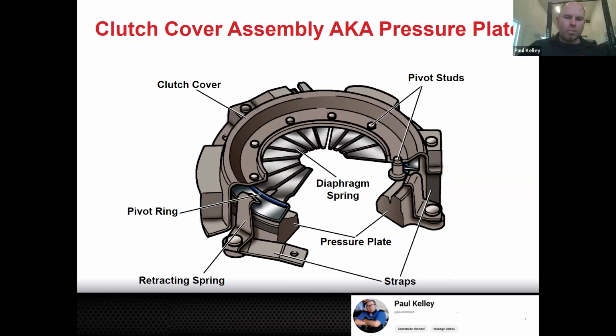Okay. So when you're pushing down on your pedal and you feel it stiff and you feel the pedal return back, that's because you're pushing on the pedal, you're deforming the diaphragm spring. And they're like, yeah, I don't want to be in this shape. So as soon as you start to let up your pressure, they're going to push your foot back. The clutch release system doesn't generally have a lot of return spring. Sometimes they'll put a little return spring in the master cylinder, but a lot of times they don't put anything in there because they shouldn't need to.